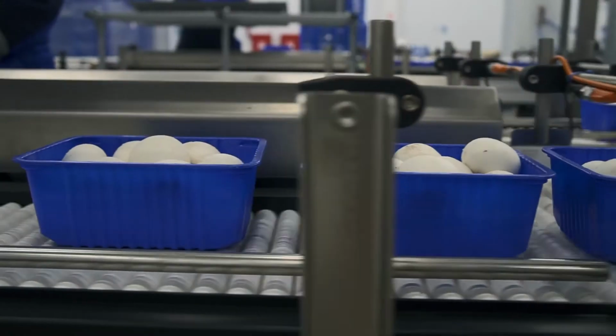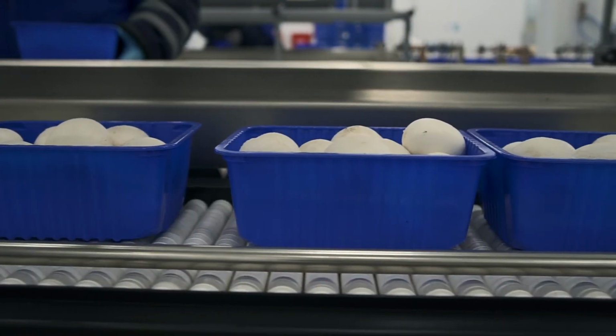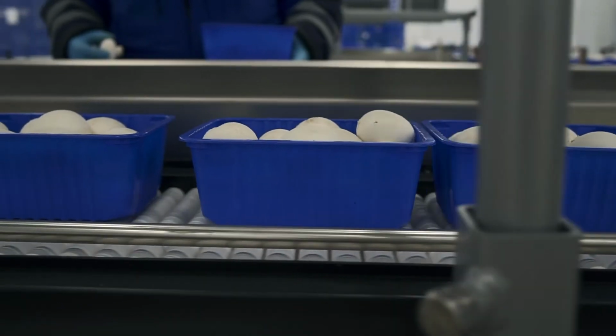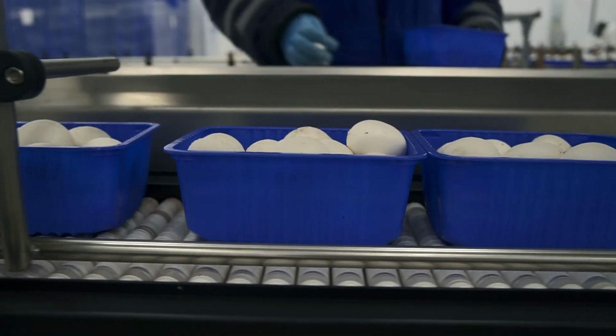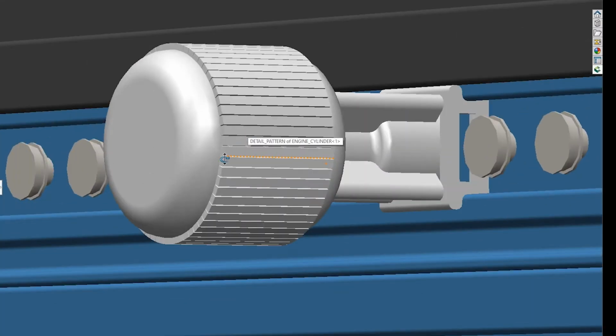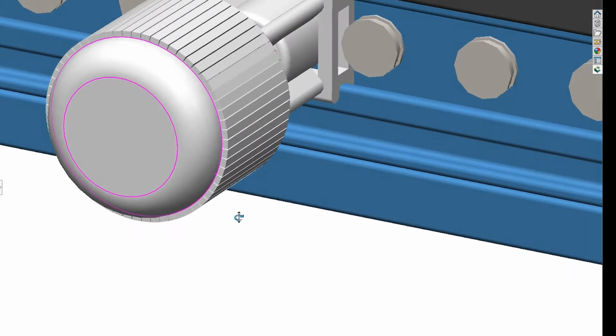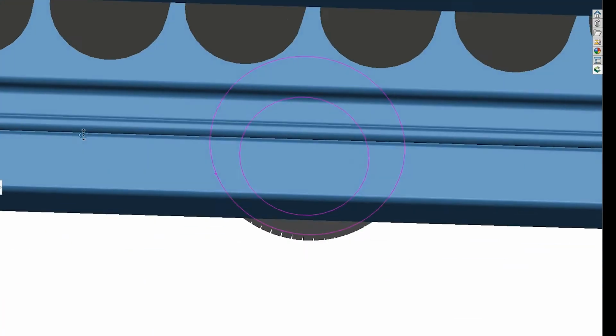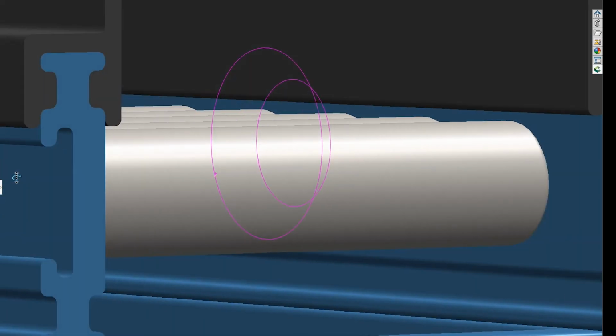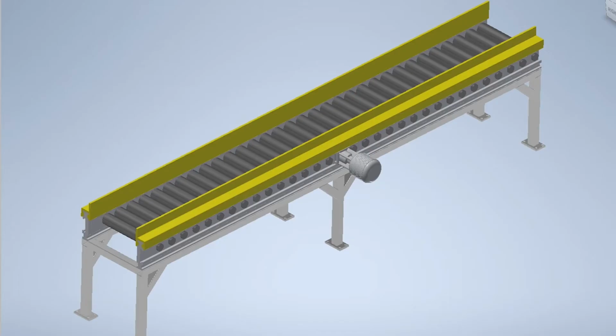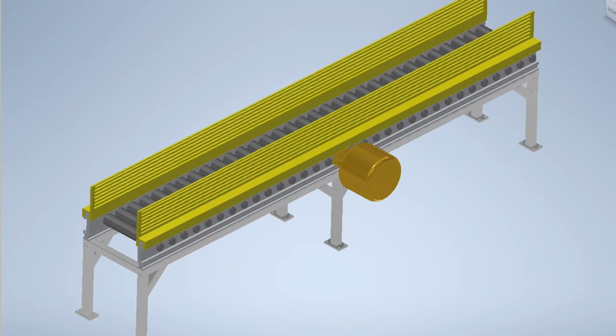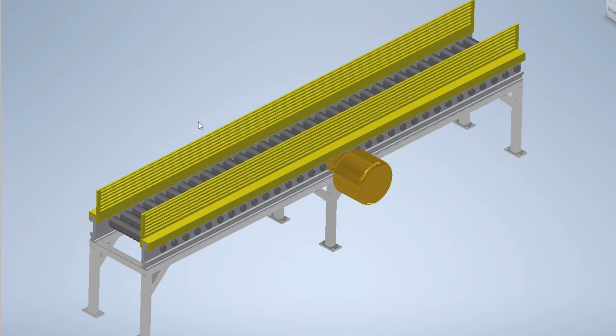it might break. Conveyor speed is important to maximize the throughput of the conveyor. Supported speed, however, requires the right engine and its rotations per minute to be selected, combined with the right diameter of the rollers. And the faster the speed, the higher the fences must be in order for the packages not to fall off.